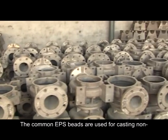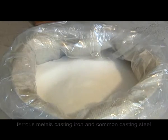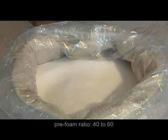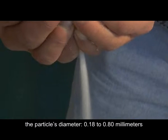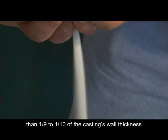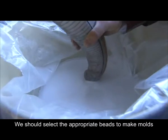The commonly used EPS beads are used for casting non-ferrous metals, cast iron and common cast steel. EPS beads feature translucent beads, preform ratio 40:60, and particle diameter 0.18 to 0.80 mm. There are 6 different sizes to choose from. The radius of the original beads should be less than 1/9 to 1/10 of the casting's wall thickness. We should select the appropriate bead to make molds.